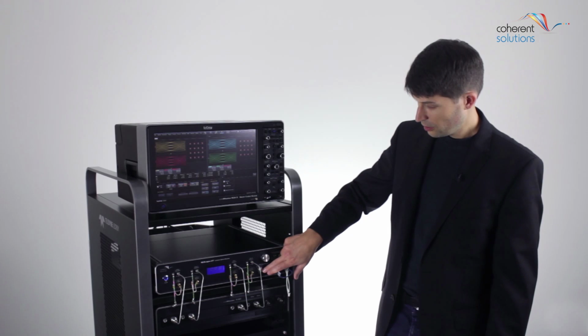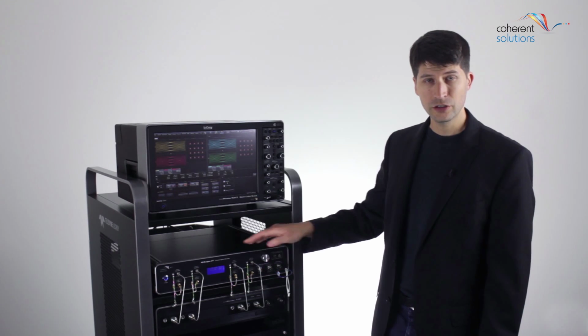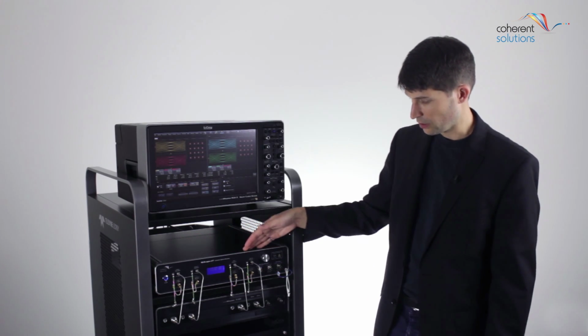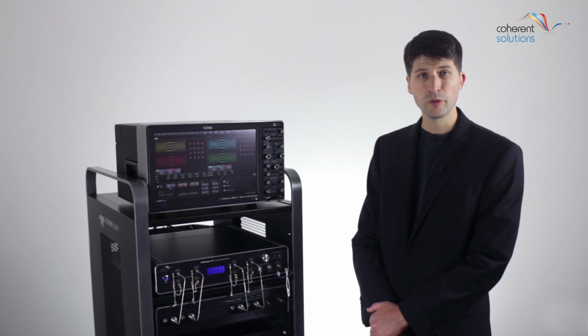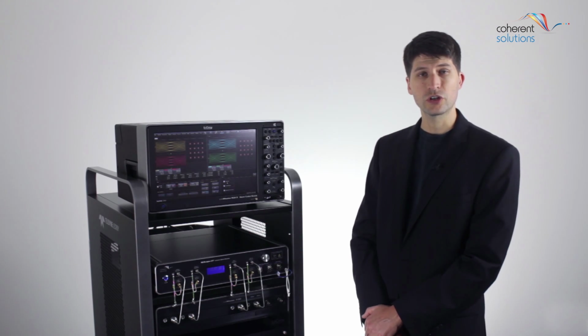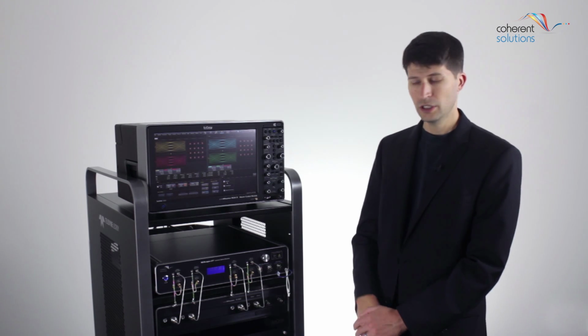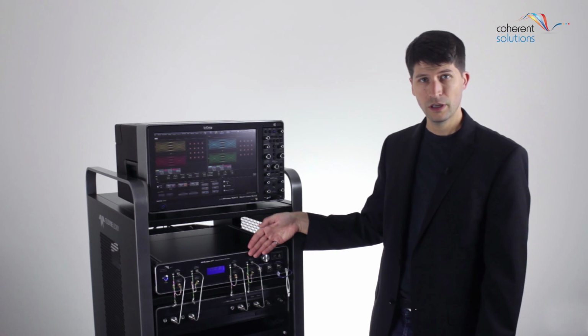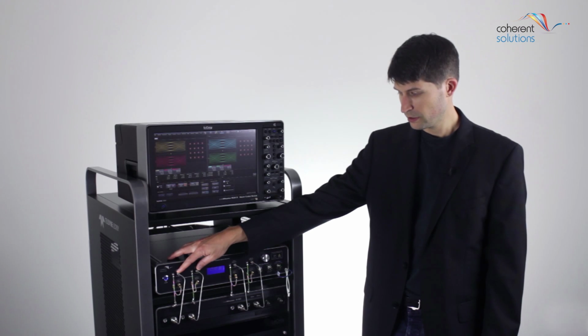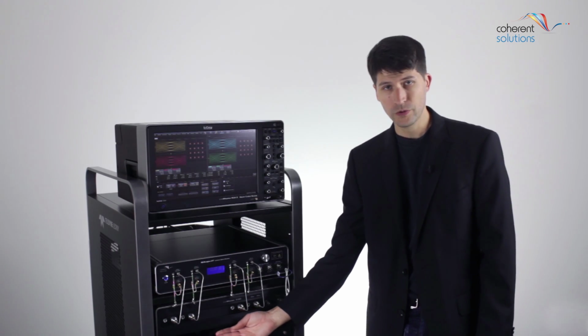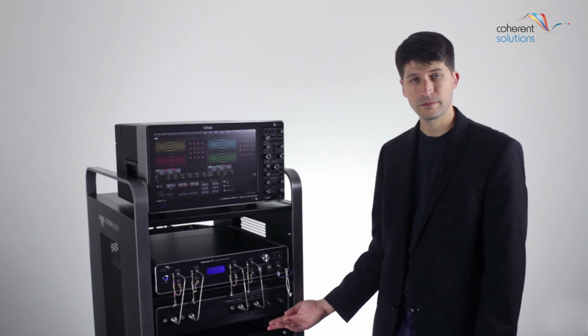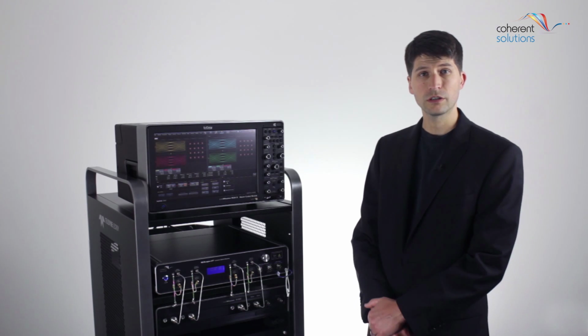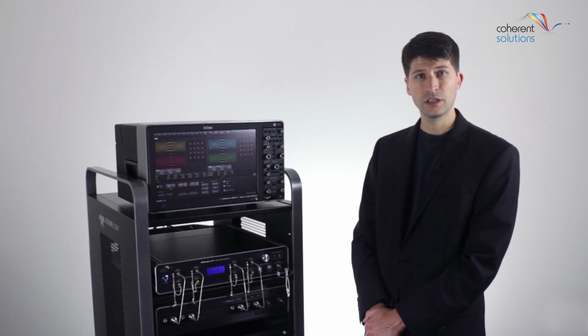We start by inserting the signal under test into the coherent receiver, which is shown here. The purpose of the coherent receiver is to convert the complex modulation format, which is an optical signal, into its 4 electrical tributaries. These 4 analog signals are then passed to the acquisition unit, which is shown here. The acquisition unit converts the analog signal into the digital waveforms.